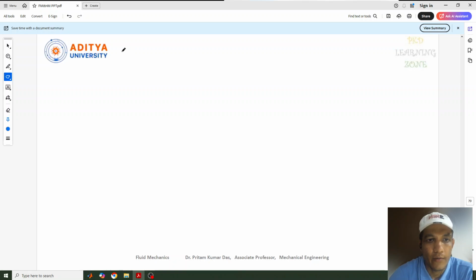So we can put all these values here. That is 3 pi mu u d. Sometimes this equation will also be written in this way, 6 pi mu u r. In terms of d, it will be written r, so d equal to 2r. So it will be multiplied in this way. So you should not be confused about that.